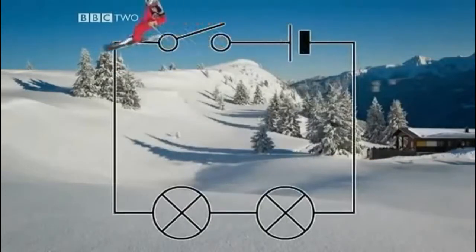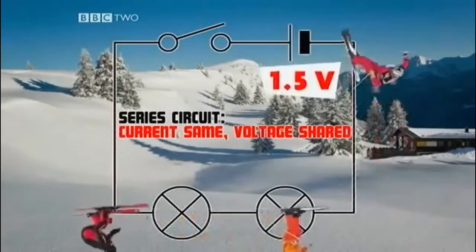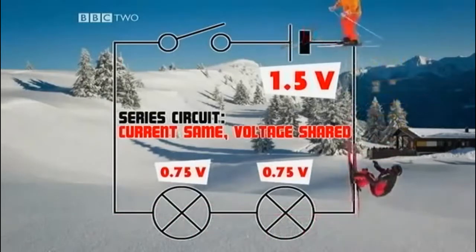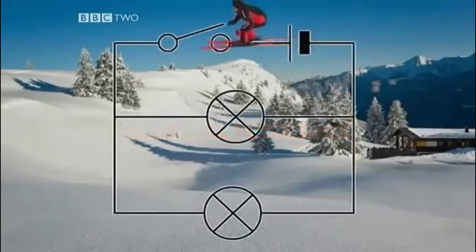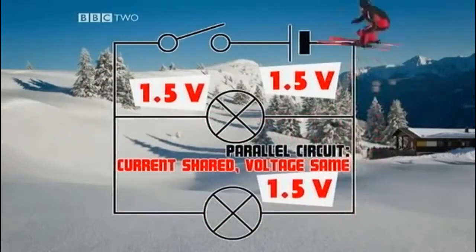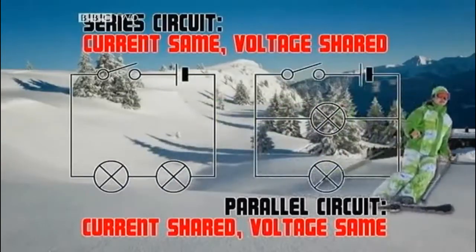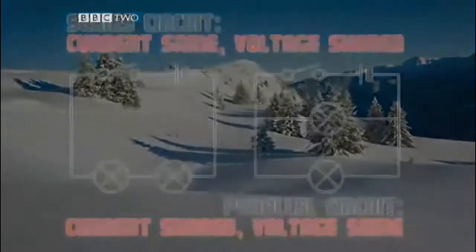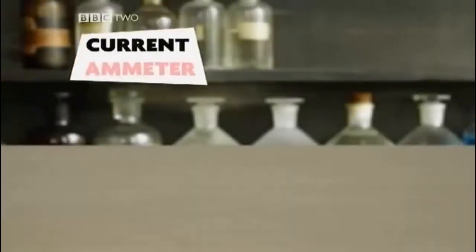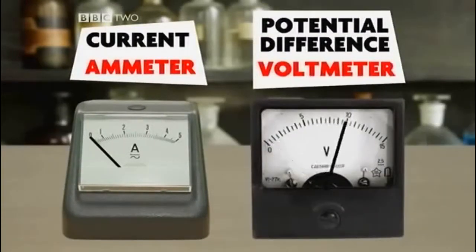In a series circuit, the potential difference is shared. So these 2 identical lamps share the 1.5 volts from the cell, half each. But in this parallel circuit, both bulbs have the full potential difference across them. So opposite things happen in series and parallel circuits. This being science, we'll measure stuff, namely the current using an ammeter and the potential difference using a voltmeter.